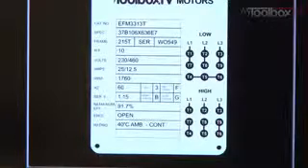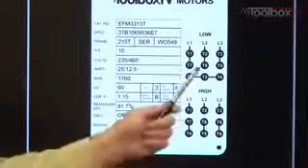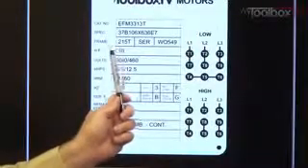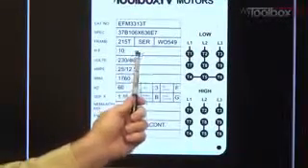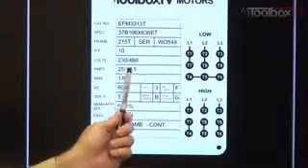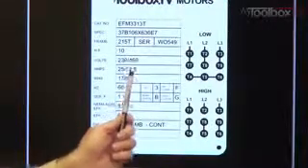Well, here we're actually changing the circuit. We're changing these connections so the circuit remains 10 horsepower. So we're keeping the wattage the same. When you do that, if you increase the voltage, the current has to go down to make the math right. And so that's what happens.